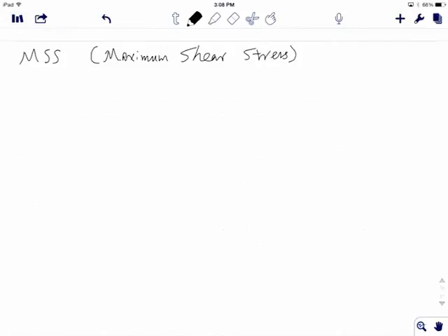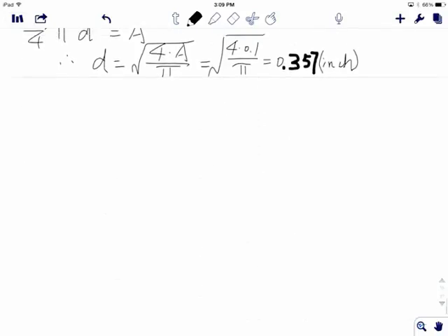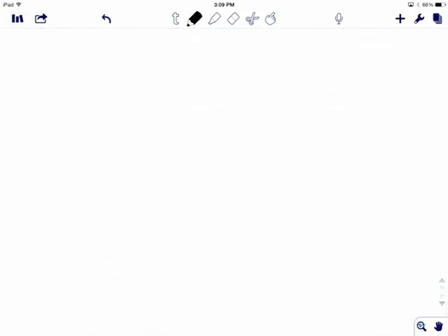And we started with, we assume it's a shear stress inside of the component that causes failure, because most of the time when failure happens, it's not a perfect 90 degrees, it's 45 degrees. And from mechanics of materials, we know 45 degrees is where the maximum shear stress is applying, right? That is when theta equals 45. So we did a bunch of analysis, and I apologize, I think I lost the notes. Anyways, luckily I uploaded that to the Blackboard. Anyways, so we came up with this.